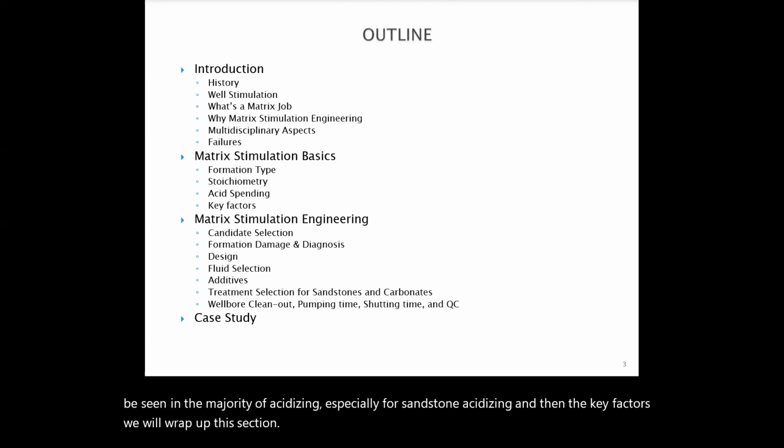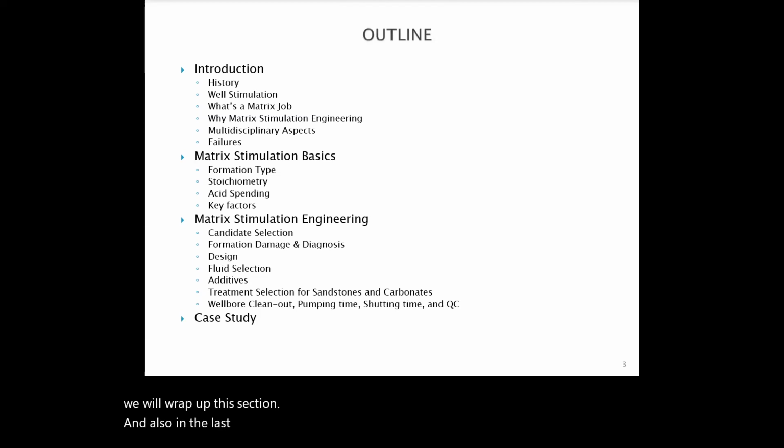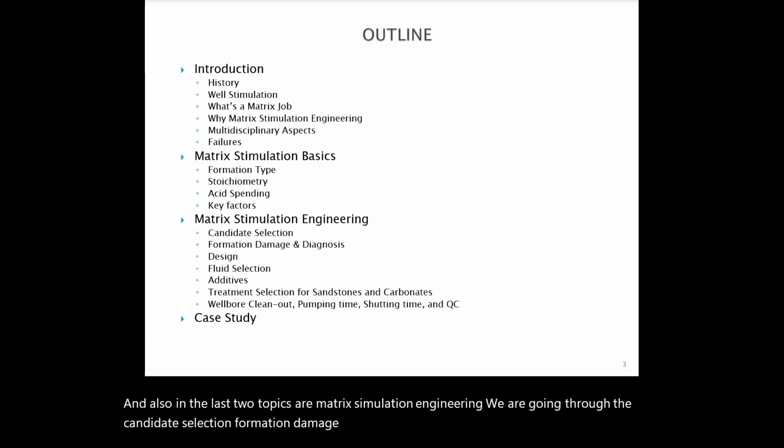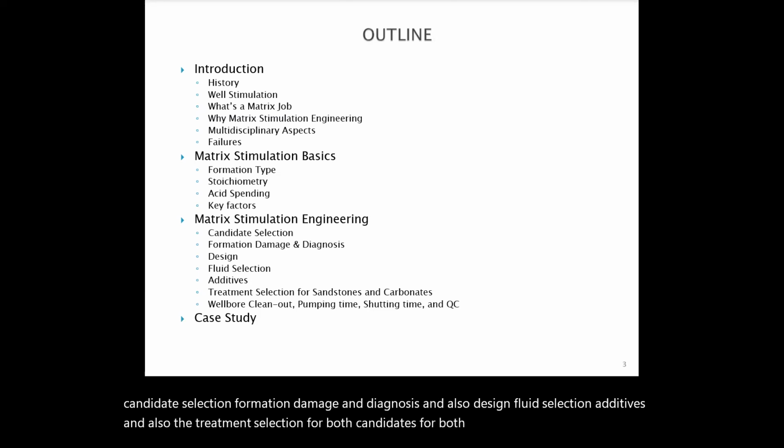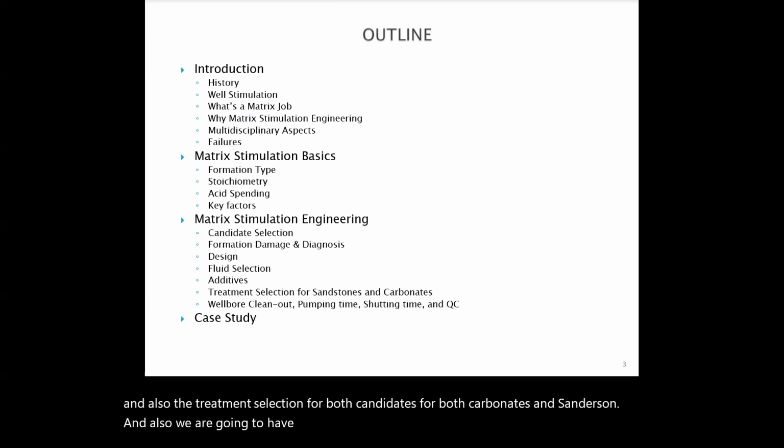And the last two topics are matrix stimulation engineering. We are going through candidate selection, formation damage and diagnosis, and also design, fluid selection, additives, and the treatment selection for both candidates, carbonates and sandstone. We are also going to have some topics about pumping time, shut-in time, and quality control before, during, and after. And finally, we are going to cover a case study.